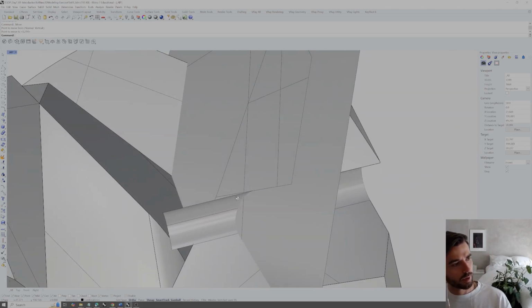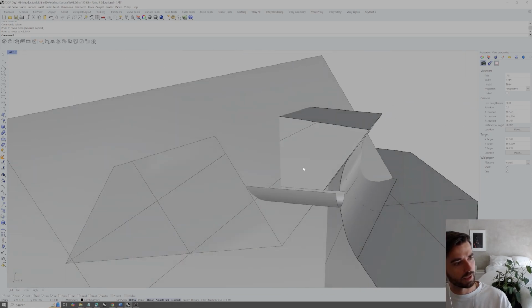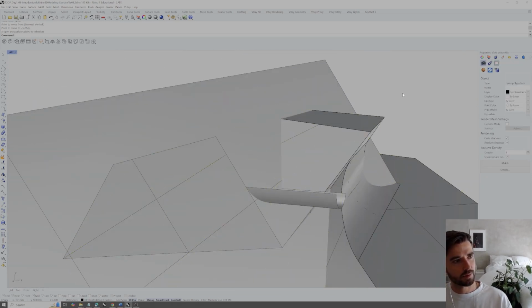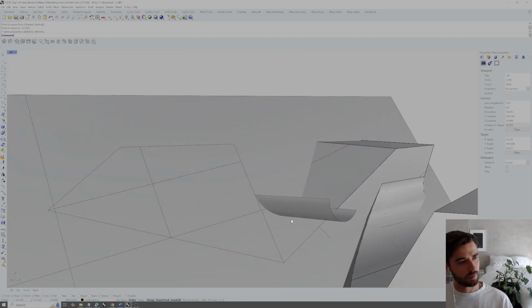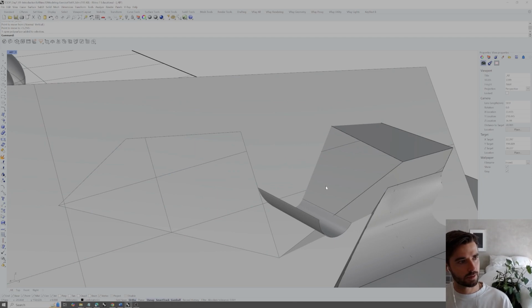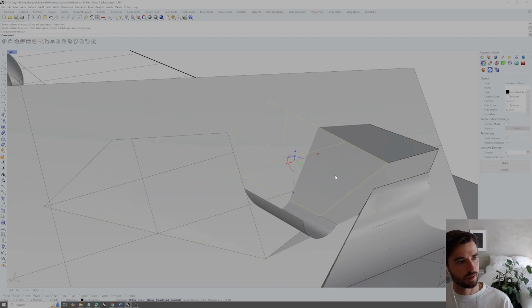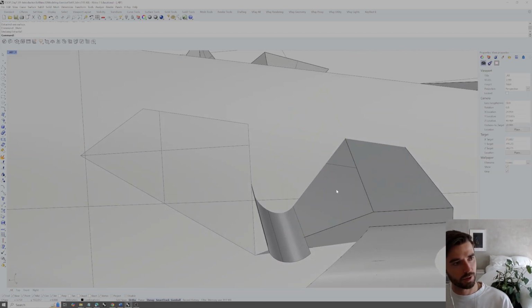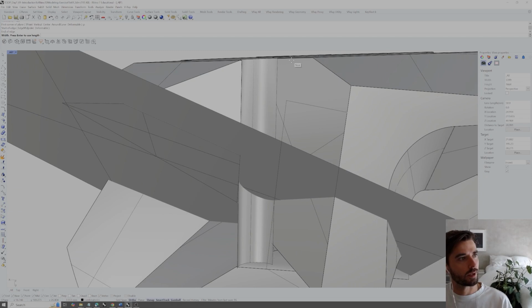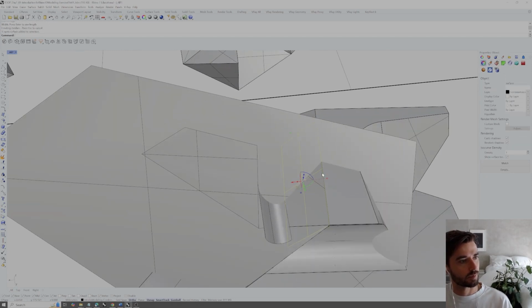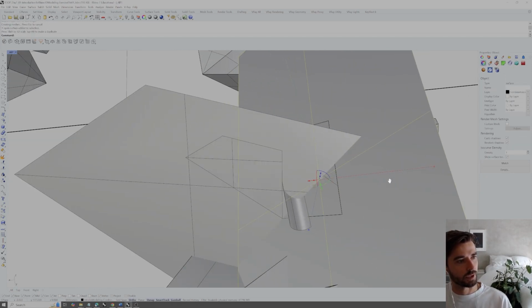This is a fairly complex one where we, I believe, just need a joining between this plane here and this plane next to it underneath. So it's going to be some edge here underneath this radius. So what we want to do is extract this other plane as well. Or even if we don't want to extract that, we can just draw out another plane, 3-point. Draw this on any 3 points of that surface plane and scale up holding shift.